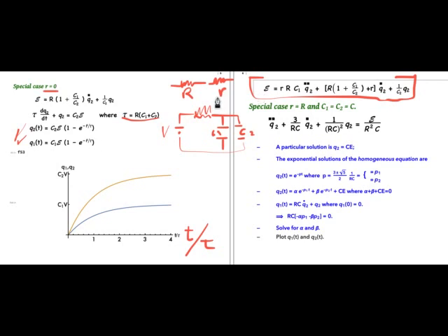All right, now let's go back to the more general case and put in some resistance between the two plates, but not keep it completely general. Let's suppose that little r is equal to capital R. So in the first special case, little r was 0. In the second special case, little r will be the same as capital R. And now again, to make it a little simpler, let's say the two capacitances are equal. So C1 is C2. We'll just call that C.